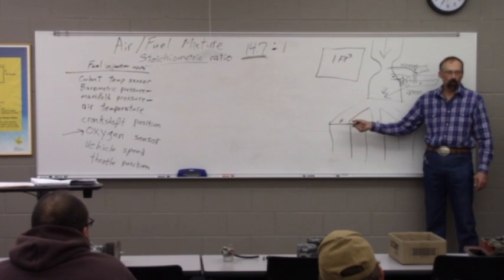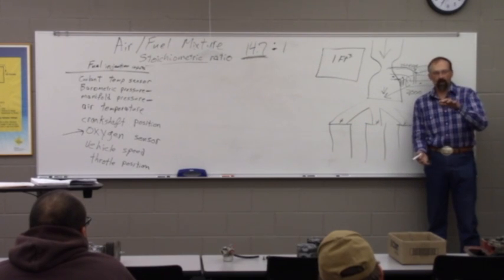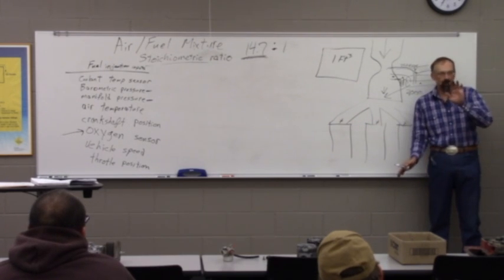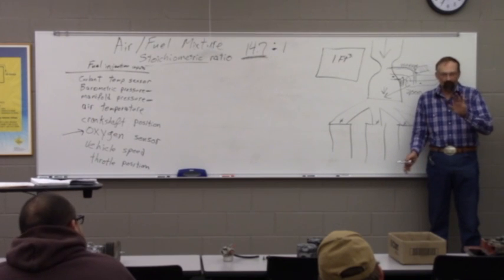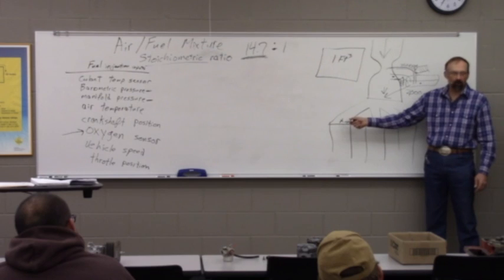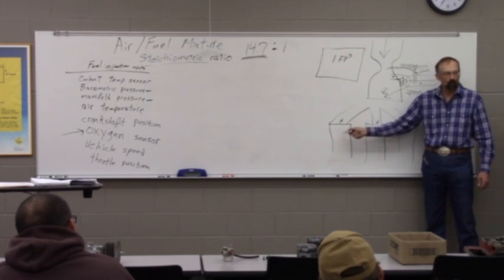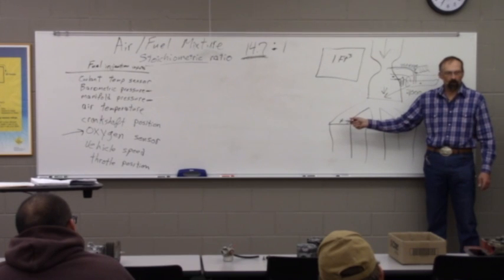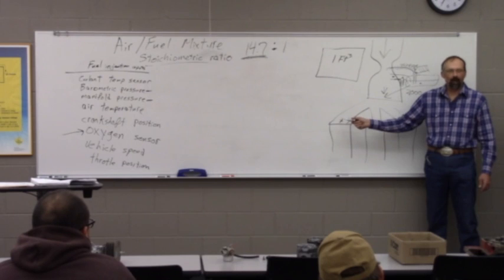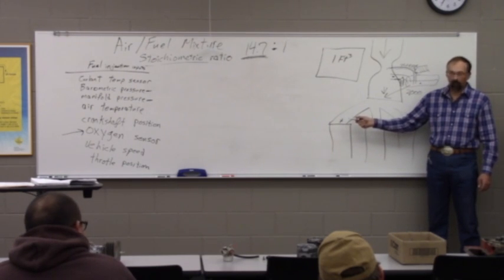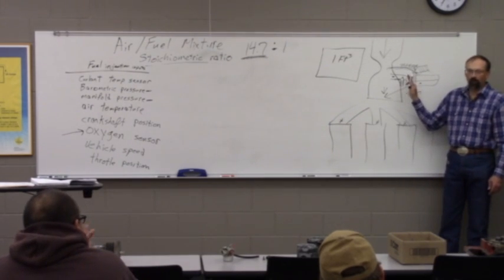Well, it's open for the entire intake stroke, plus a little bit on each end of it. So a little bit over 1/4 of the time, this valve is open for air and fuel to flow into this cylinder, but the injector was flowing all the time. Well, not the best, but it was still an improvement over what we had before.